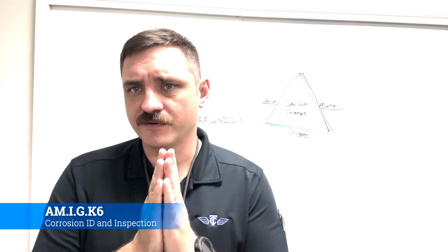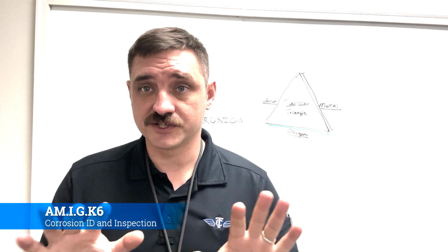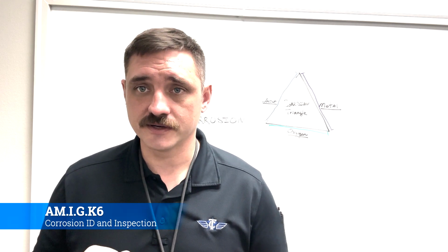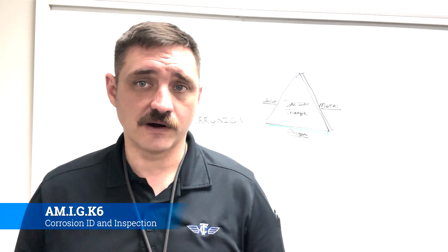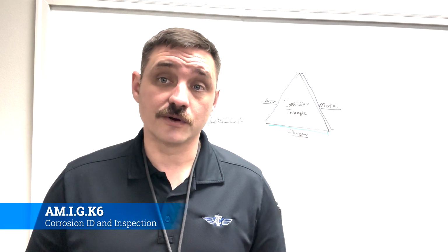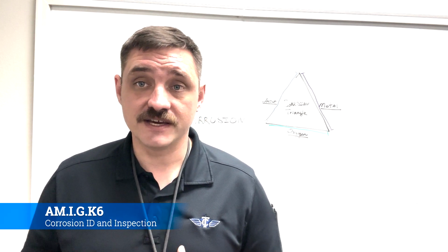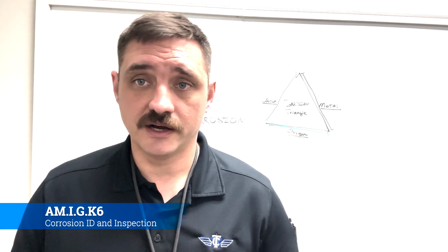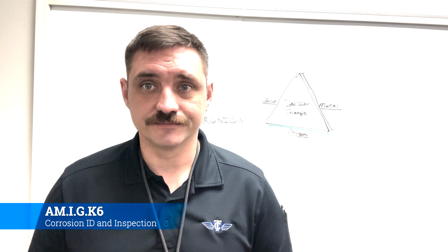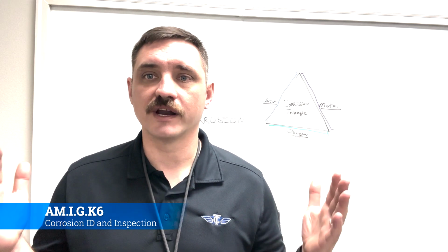But once you got to the point where you can't see it or touch it or feel it anymore, how else do you get to it? Well, your mirror and a flashlight will get you into crooks and crannies, but that'll only get you so far. And a lot of times corrosion will often be found via NDI. So that's either ultrasonic, dye pen, mag particle, what have you.